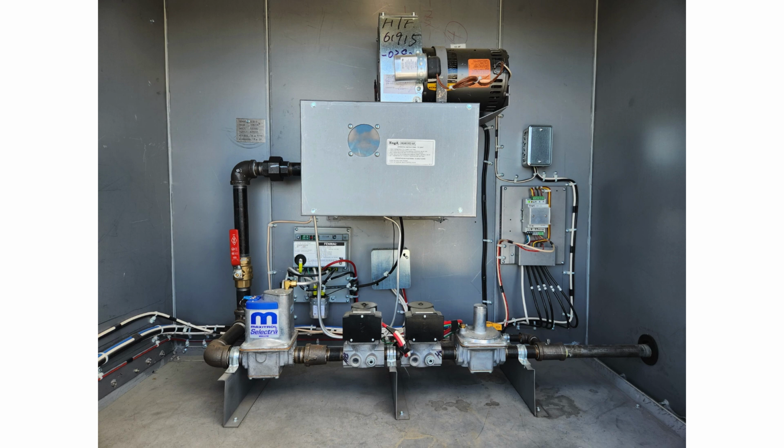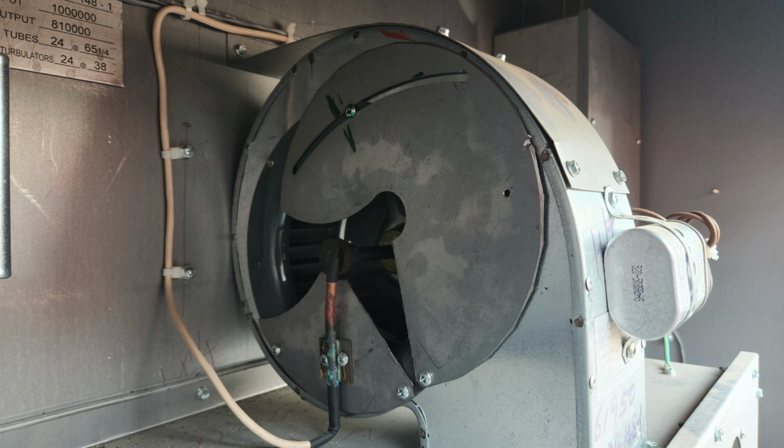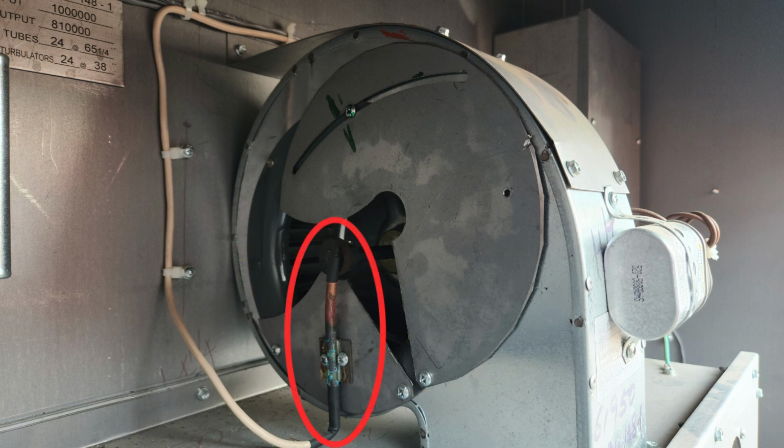The common components associated with the burner manifold typically include the pilot valve, manifold pressure regulator, main gas shutoff (there may be one or two of these), modulating valve, and main manual shutoff valve. There are also two test port plugs located on the inlet side of the manifold upstream from the regulator and on the elbow just before the piping enters the burner box. The combustion blower is located on top of the burner box. On the side of the combustion blower is an adjustable inlet air slide, the Pac-Man, and the combustion blower speed sensor and magnet.